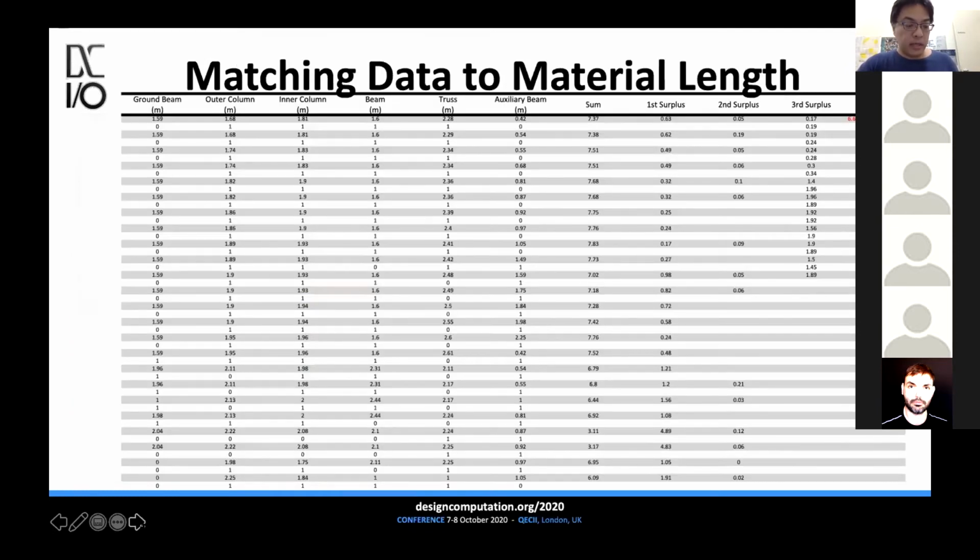The length of the CLT panel supplied by the supplier is 4 meters, and the wood sheet is 5.7 meters. We use the Excel Solver add-in to find the optimal pairing values matching the CLT panel length based on the material specification. We can reuse the maximum surplus material through the pairing process and purchase the minimum amount of material.